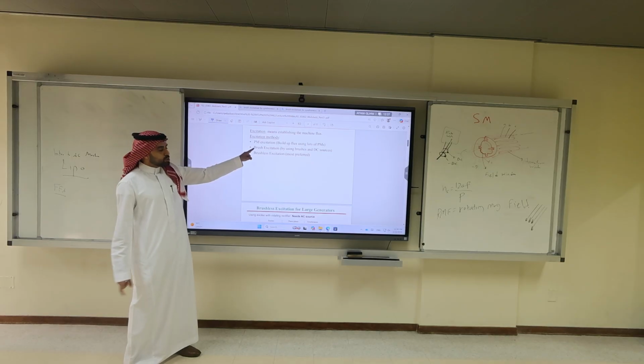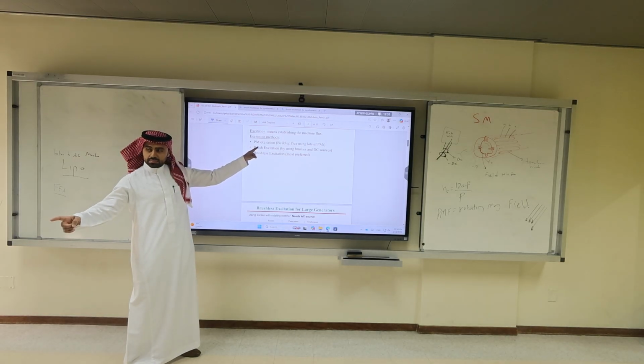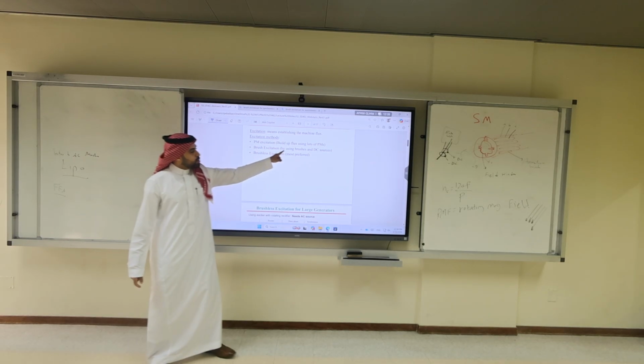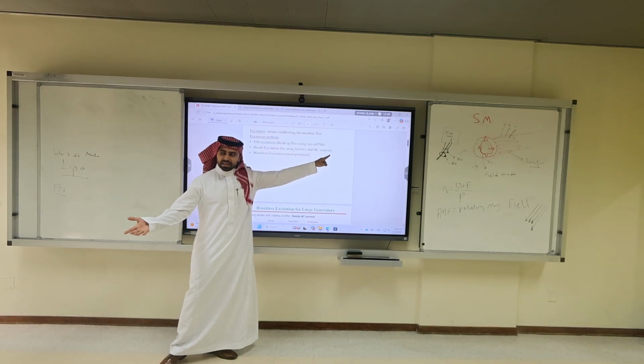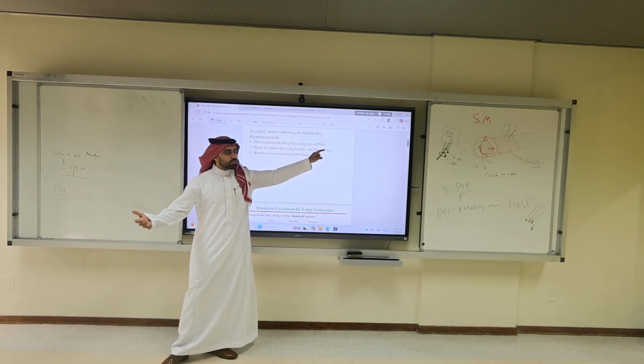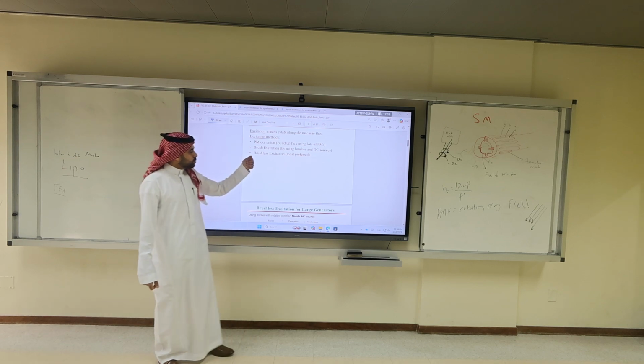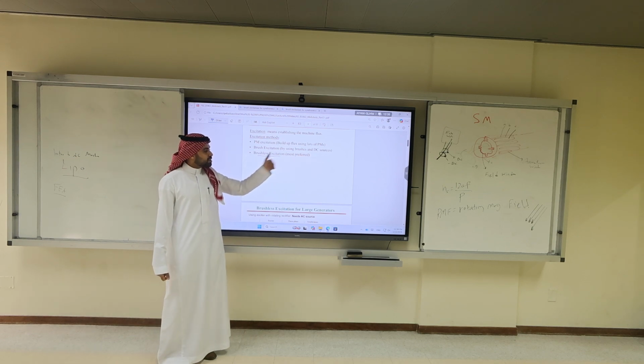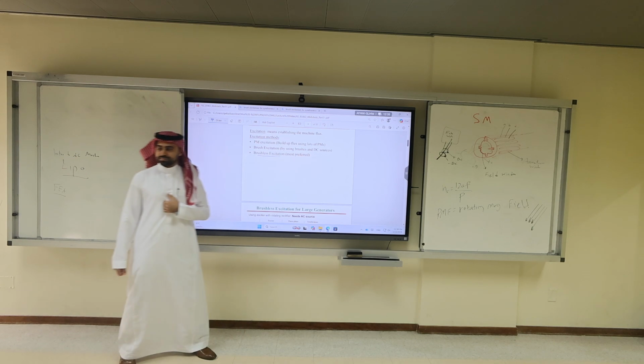You use batteries for brush excitation. For brush excitation, using brushes and DC source, which is a small battery. But let's say you don't have a battery, what should you do? You use the brushless excitation, which is the most preferred.